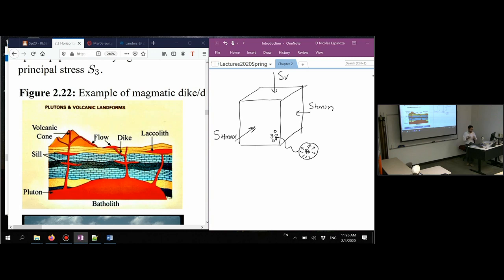Well, in this particular location, for the way in which this dike is propagating, opening against the rock as a vertical fracture and pushing horizontally, what you're saying is correct. The minimum pressure required to open that fracture is going to be the minimum principal stress.